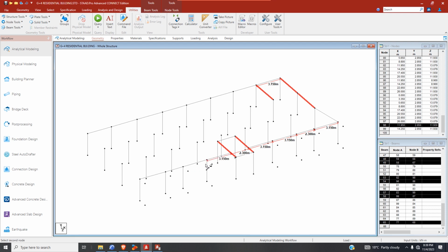The architectural plan, you can see again, there are no columns. The columns are starting at the first beam. So I will do transfer repeat in the Y direction. So my story height is 2.85. Then I will stop. Then I will move back to this view.